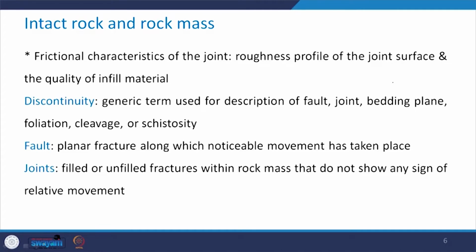Frictional characteristic of the joint, what is it? Because we have already discussed the intact rock, but this aspect, the frictional characteristic of the joint, we have not discussed yet in detail. So, basically this is the roughness profile of the joint surface and the quality of the infill material.